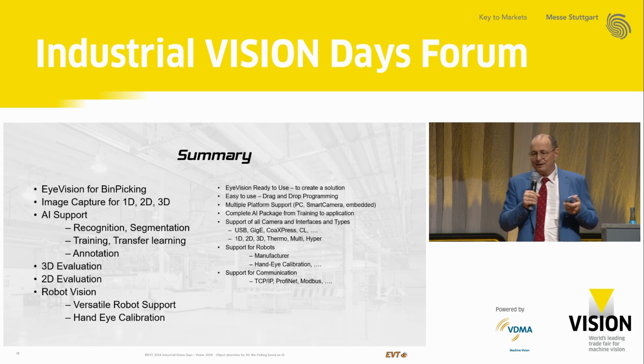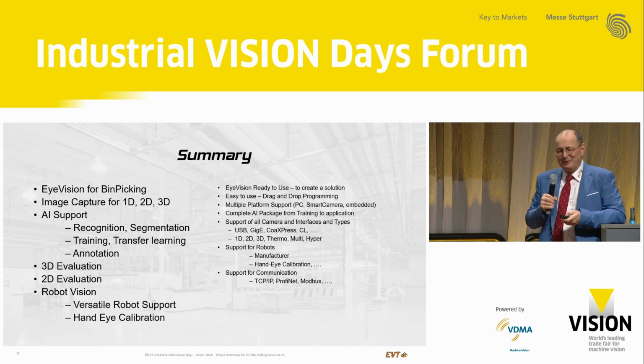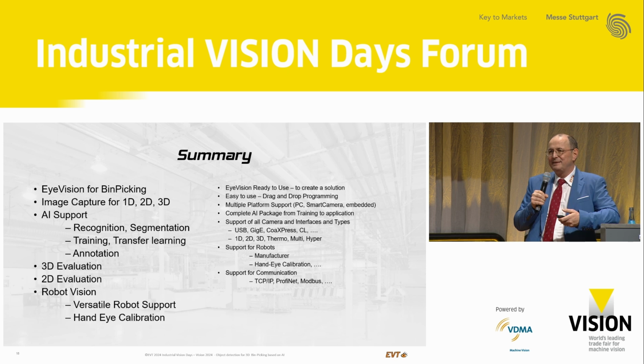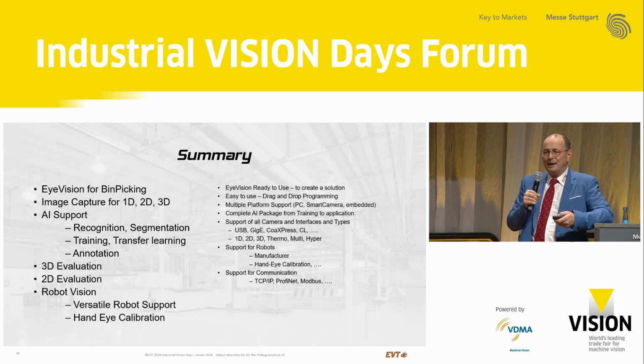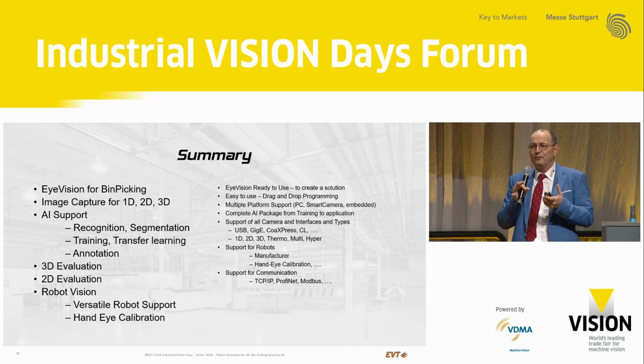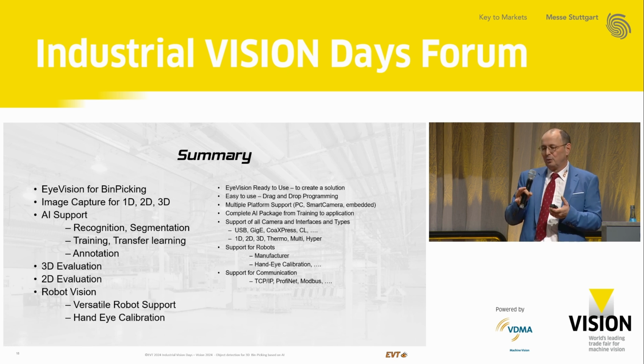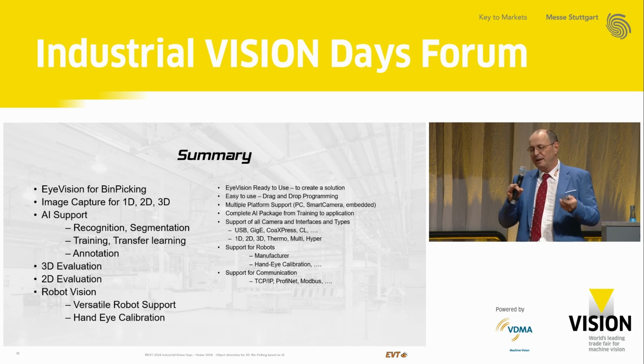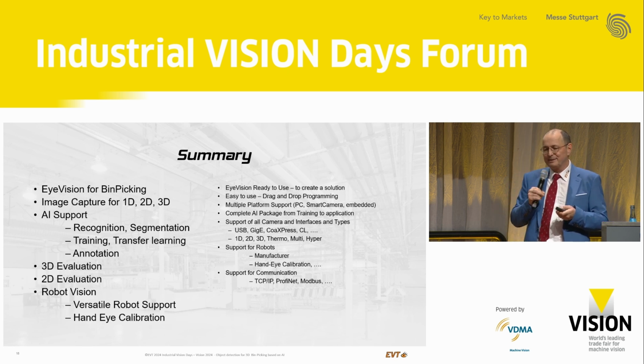And for the summary, for really easy bin picking, it's much easier if you use this combined technology, because you get two kinds of information. So one, to select the part, even if it's shiny and it's difficult to segment it in 3D, and then you use the 3D and the hand-eye calibration to make the solution with the software.